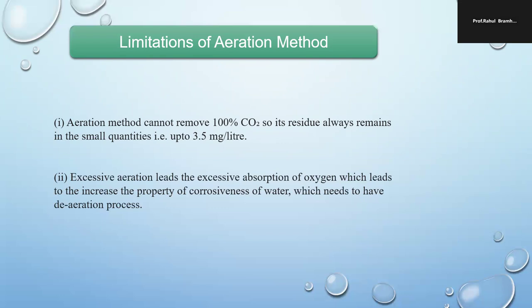Sometimes in the aeration process, excessive absorption of oxygen is done. At that time we need to have a de-aeration process, to decrease the corrosiveness of water. So these are the two limitations of aeration.